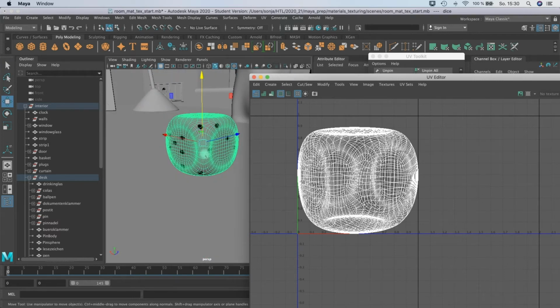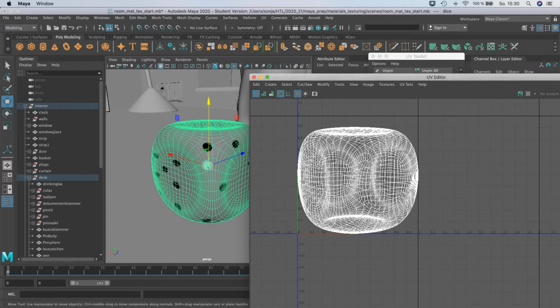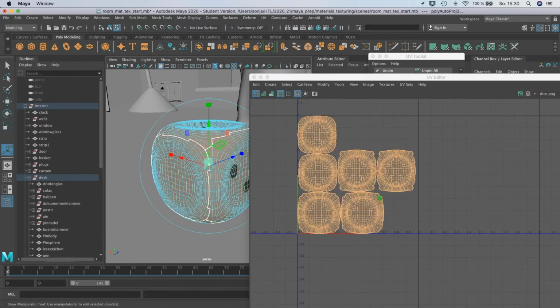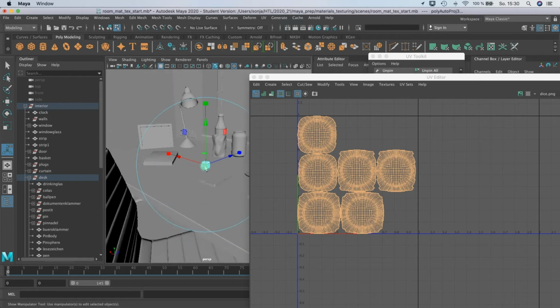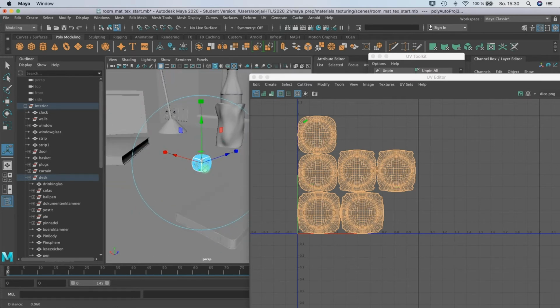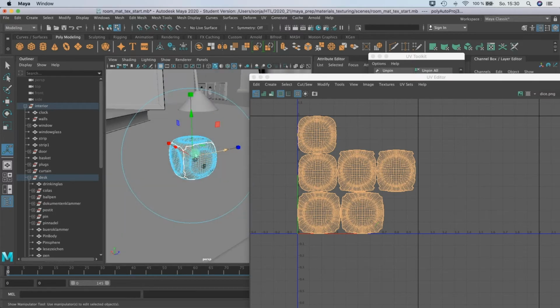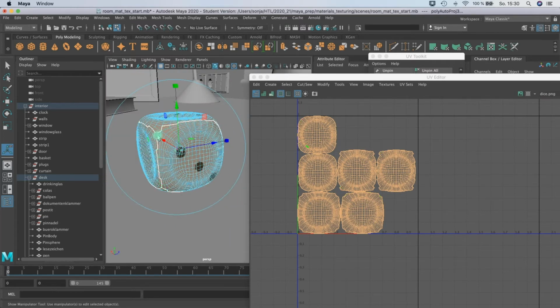One of the things that we could do, just for when you don't see the points, press 6 on the keyboard, because between 5 and 6 you can change that you see the image. Good. Here in the image we see we have messed up everything, and the first thing that we test is the automatic mapping. I selected it in the object mode, and this maps from 6 sides and tries to get the most appropriate result. It's a cubic mapping, and of course you see it does a little bit strange cuts.